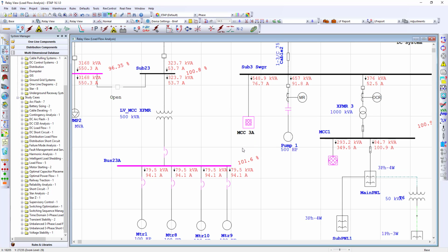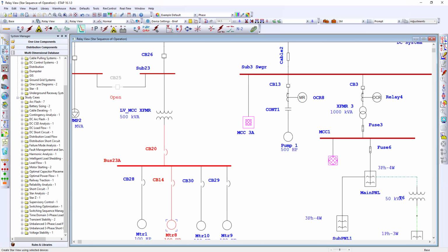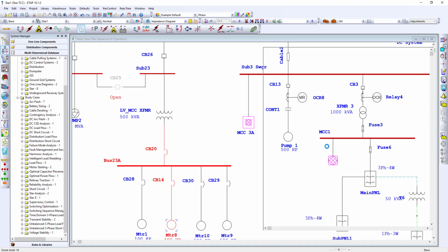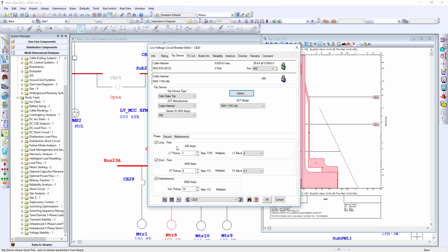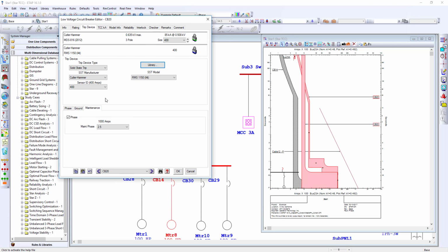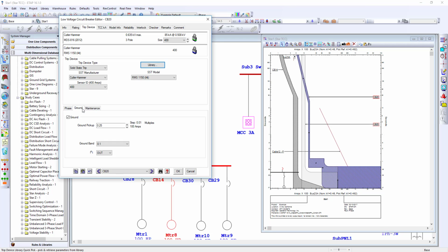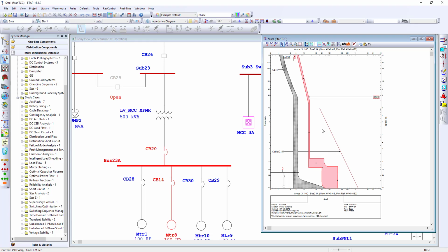So what we're going to do now is let's go ahead and pick my main protected device and the largest load breaker, which in this case all the load breakers happen to be 100 amps. I'll go ahead and create a TCC. There's that TCC. I think what I have is the maintenance mode. It automatically came enabled. There it is. Click OK. And there's my coordination curve.